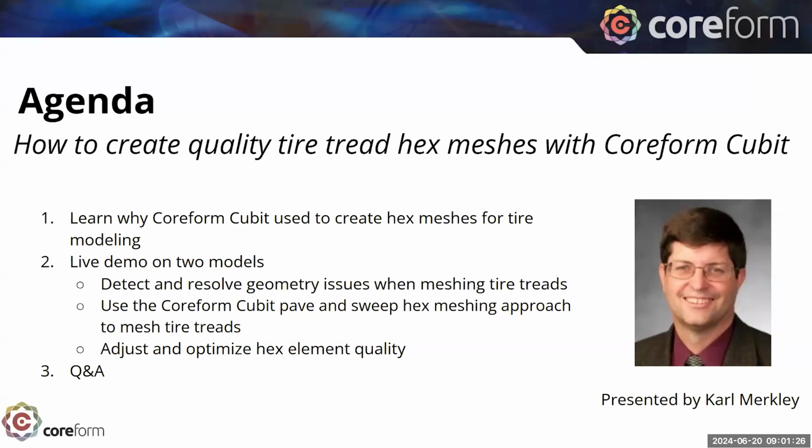First of all, introducing Coreform Cubit and discussing why this software has been used for decades to create hex meshes for tire modeling. Then Karl will demo live on 2 models some key features with Coreform Cubit. So we'll be focusing on how to detect and resolve geometry issues when meshing tire treads, specifically how to use the Coreform Cubit pave and sweep hex meshing approach to mesh tire treads, and then how to adjust and optimize